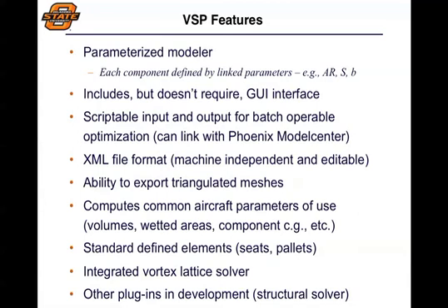And you couldn't do that, for example, in a CAD program without defining what those parameters are already. I mentioned it has a GUI, but doesn't necessarily require it, and we'll give an example of that as we go through the demo. And it has scriptable input and output, as I mentioned before as well. One of the things we use occasionally is something called Model Center, which is an optimization program which allows you to run through lots of parameters and say, okay, first, I want to look at a range of spans, for example, and generate models for certain spans and then do the analysis on that.